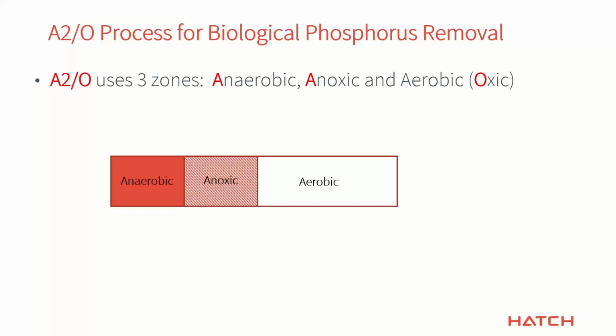So I just thought I'd do a real quick summary of what the A2O process is. This is for doing biological phosphorus removal. This is a system that promotes the growth of phosphorus accumulating organisms by having an anaerobic zone and then also an aerobic zone. So we'll get the PAOs, they'll suck up the phosphorus and then be able to be settled out in the clarifier and removed. At the same time, this process also does nitrogen removal, and the aerobic section will have nitrification happening, and then there will be a recycle to the anoxic zone where they'll have denitrification. So we're getting rid of both nitrogen and phosphorus all together in this same process.